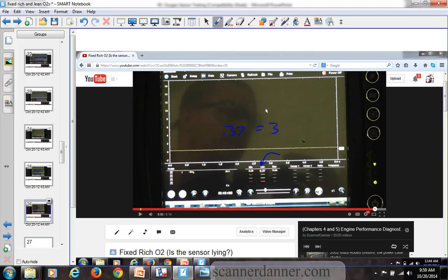That equals 370 millivolts. Does that contradict the number I just gave you? I said sensor grounds, 100 millivolts or less. Is the heater ground a sensor ground? I know it's part of the sensor, but it's not a signal ground. It's a load, 1 to 2 amps of current. You're going to have higher ground voltage on higher amperage circuits. That's normal, that's good.